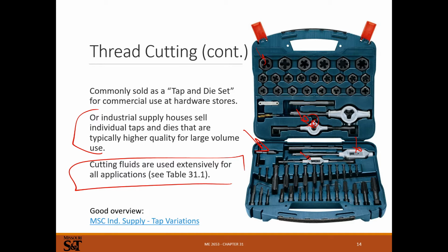I usually don't like buying nitrided taps because they're going to wear out and need to be replaced at some point in time. So a really good quality high-speed steel set, something that's U.S. or German or Japanese made, is what I highly recommend for taps, because the risk of them breaking is usually a lot more than the cost of having spent a little extra money. So yeah, buy nice taps.